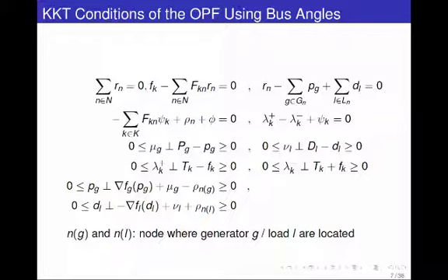And now, if you remember right, we had this lambda back in the economic dispatch problem. Now the role of that system lambda is taken by this rho of that location. So N of G here is just the bus at which this generator is located. So now we used to have a global lambda. That's now replaced by this rho of a given location. It's not a lambda that's common to all the network anymore. It's a rho that's specific to a bus.